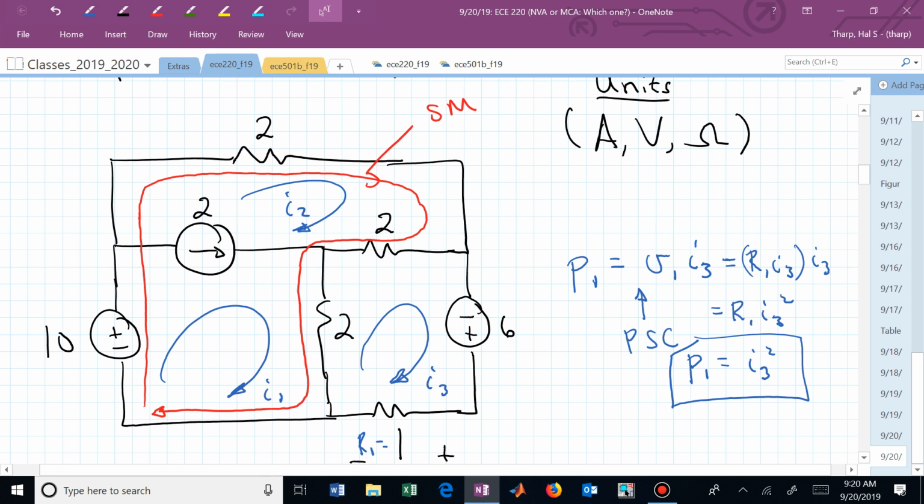It's I sub 2, but we're going in the opposite direction with I sub 3. The net current through that 2 ohm horizontal resistor, going left, is I sub 2 minus I sub 3, because it's shared or in two meshes. So you're going to have two mesh currents determining the net current in that resistor, depending on which direction we're going.